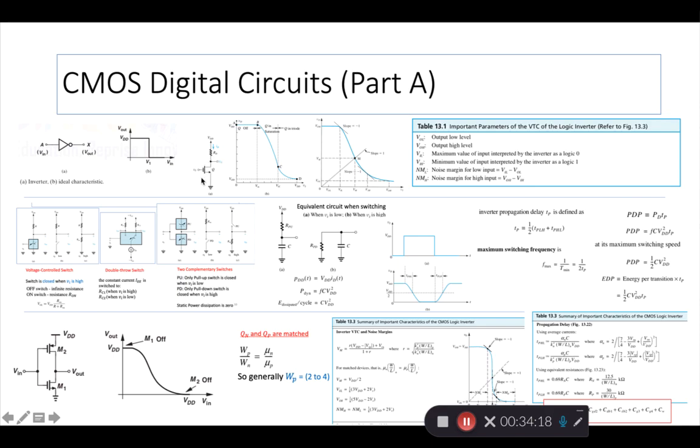We also introduced the idea of a semiconductor device, the NMOS transistor, that can function as an inverter because it has this nice VTC that has this inverse shape, and hence we can make the device work in this region where it's off and in this region where it's in saturation or on, or triode, right?